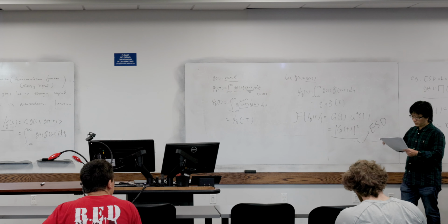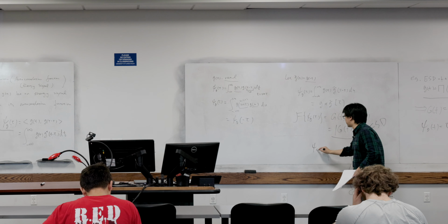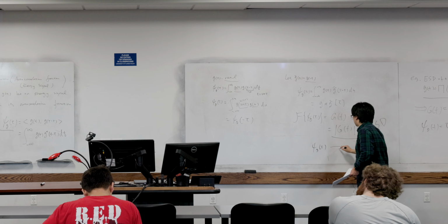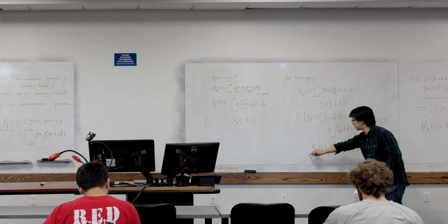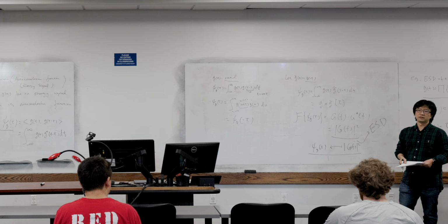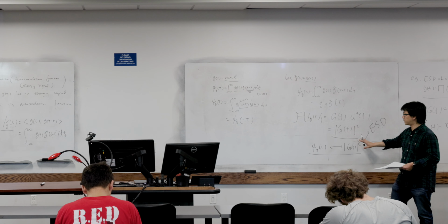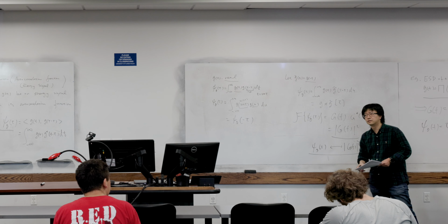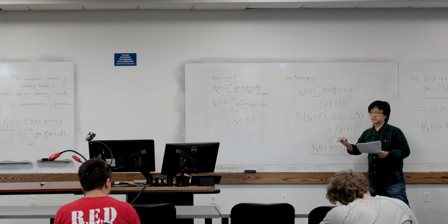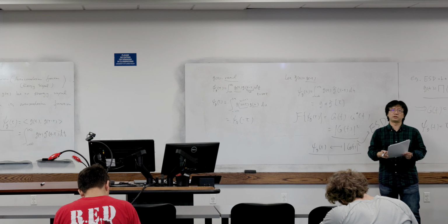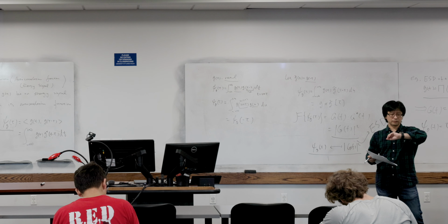So now we have a very nice result: the autocorrelation function and the energy spectrum density are a Fourier transform pair. So if it is hard to compute in the frequency domain, we can do that in the time domain and vice versa. This is okay for deterministic signals, but this concept is extremely important for random signals, which we may talk about in the next lecture.